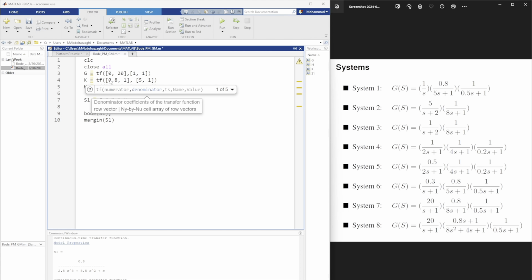In the denominator, by the way, I have a second order system, starting with, again, highest order of S. So 8, 4, and 1. That would constitute my system. And if I want to make sure that my numerator and denominator have the same order, I need to add a 0 to the numerator to make sure that this starts with a 0 S2. The last one, 1 over, so this would be 1 over half S plus 1. So this is exactly half S plus 1.